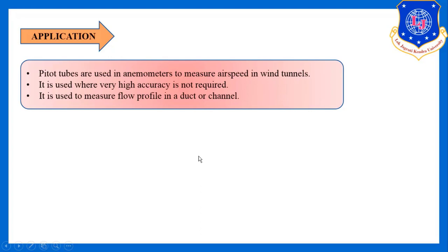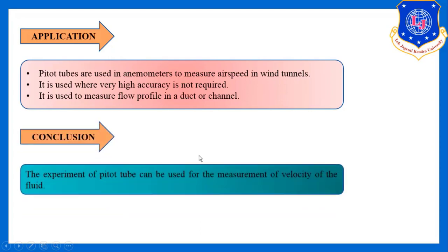So what is the conclusion of our experiment? The Pitot tube experiment can be used for the measurement of velocity of the fluid, and from that fluid velocity we can calculate the flow rate of the fluid.